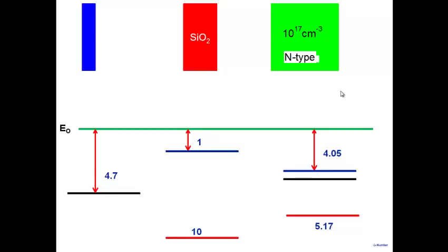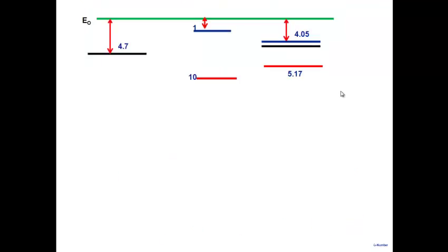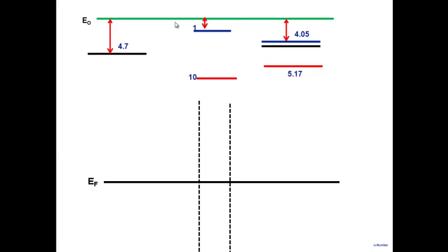Okay, shall we look at the solution? All right, so let's see. First step, constant Fermi energy. Let's draw it. Now we have two interfaces, so let's draw two lines here, one interface here and the other interface here. Again, far away from the interfaces, everything is fine. So we can locate this here. EC will be very close to EF here, and EV again we can locate.